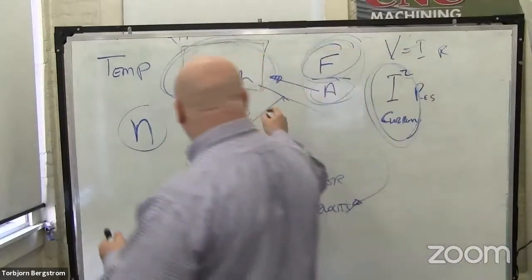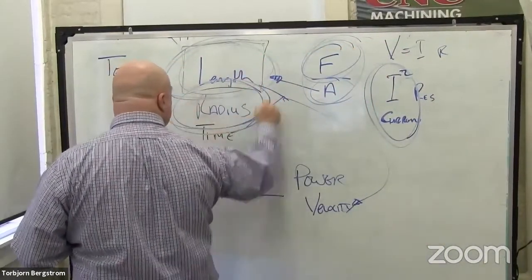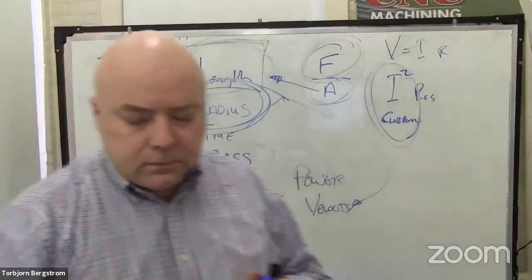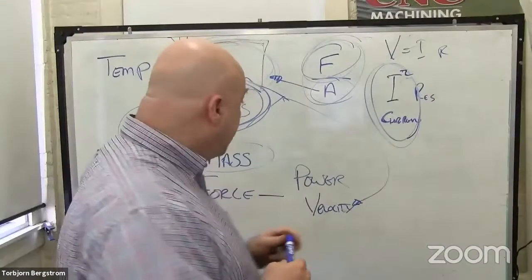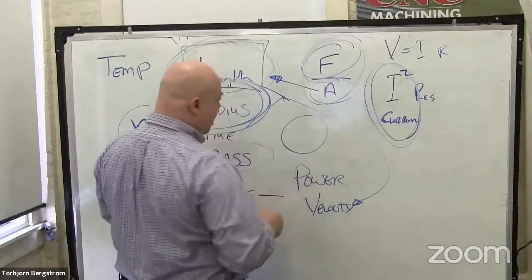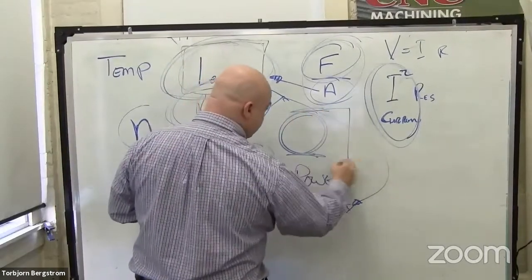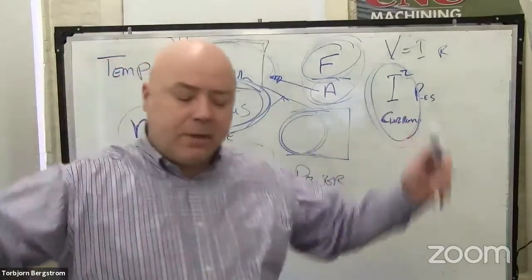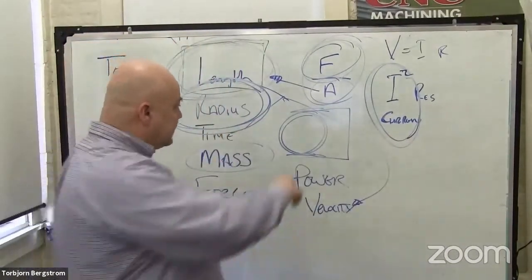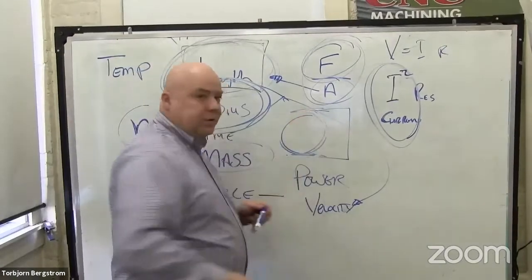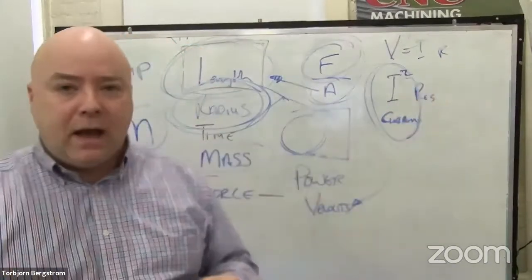How do you measure radius? You measure the respective diameter of the part that you want to know the radius for and divide that number by 2. Okay. So if you have a round part, you can measure the diameter with some sort of diameter gauge, right? Calipers can do it. We use a micrometer. We can actually wrap a string around it, measure the circumference by finding the length of that string and calculate the diameter back, right?